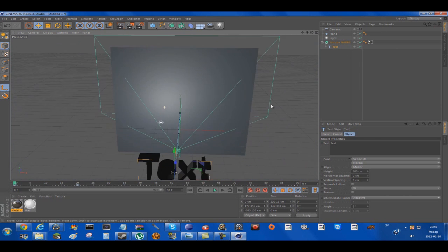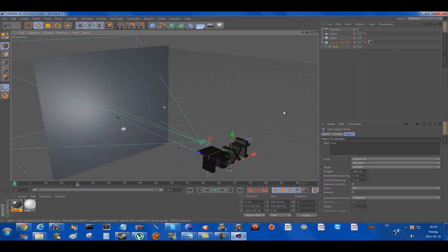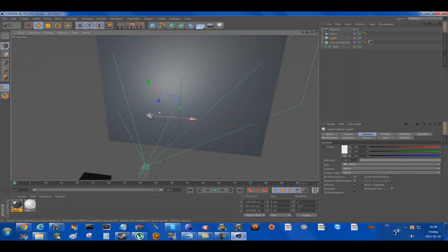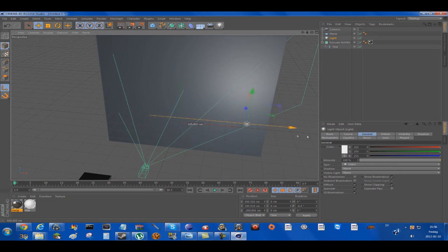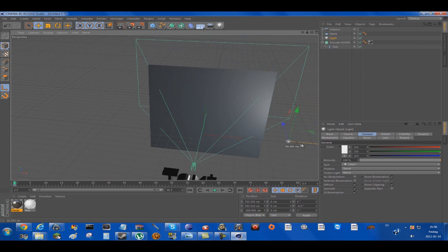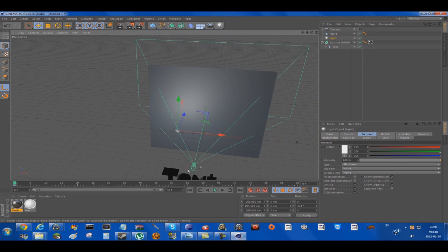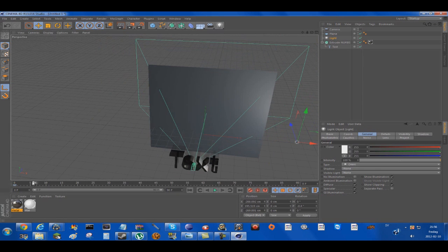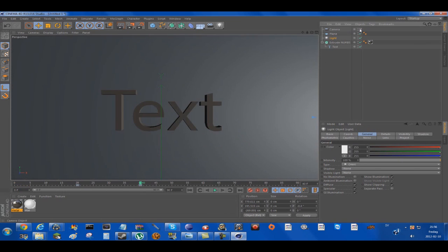I'm pretty new to Cinema 4D, but I started to understand the program. So let's show you another thing. Okay, it's gonna make an animation for the lighting right when it's entering the position. Click on the key. You have to do a different animation for every object, so that's the annoying part. And you can move it right there about, let's see, 40 frames, and put a keyframe. You can move these keyframes, so don't worry. Right after the text comes, the lighting will come too. So let's do this. Go into the camera mode here and go back.